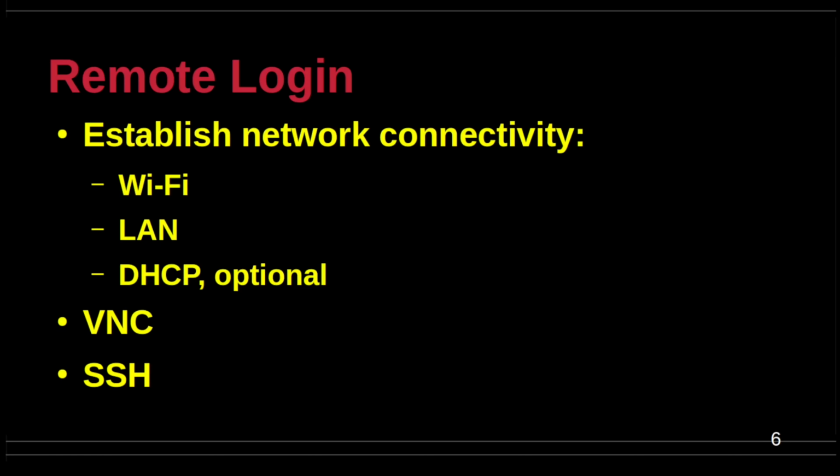Once the Wi-Fi and Ethernet connections are operational, you should use a VNC viewer on your desktop to connect to the board. Similarly, use SSH. Remember, the address will have changed if DHCP is enabled for the command line access. Finally, depending on your environment, it is always good practice to change the logon credential. Use the ifconfig command to review your revised network connectivity information.